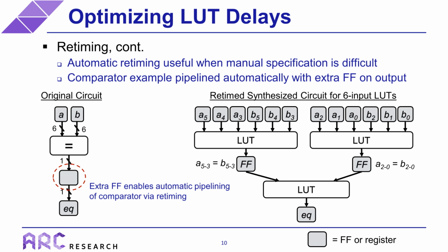Now, I've never thoroughly evaluated automatic retiming across different synthesis tools, so I can't give you exact guidelines on when to use automatic retiming versus manual retiming. So my suggestion is to evaluate it in a modular fashion to see if your specific synthesis tool will do what you want on individual pieces of your design before you waste time creating a huge design only to find out that you have to manually move around registers to do the retiming yourself.